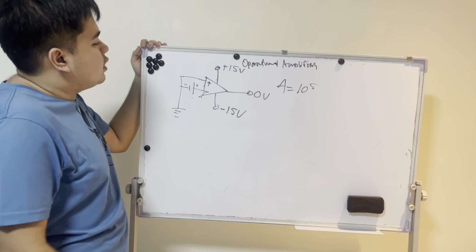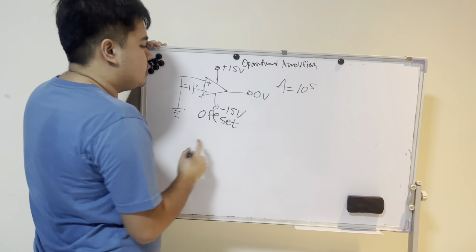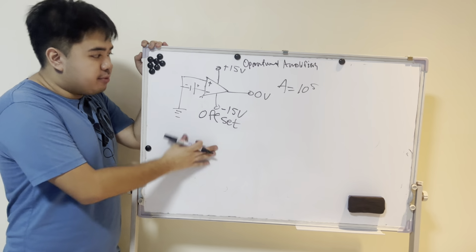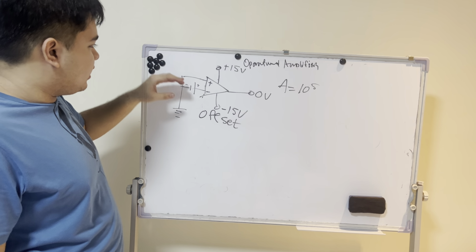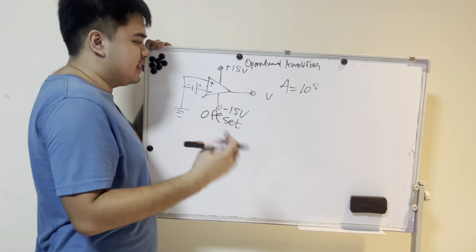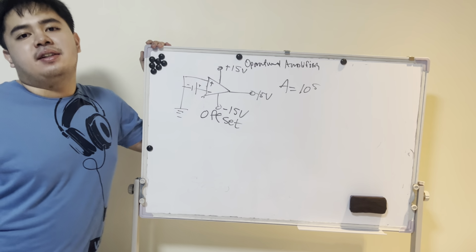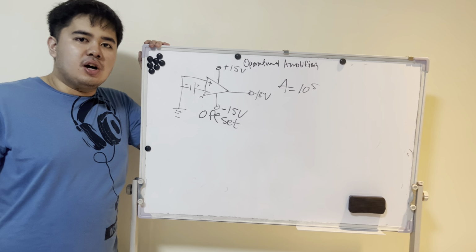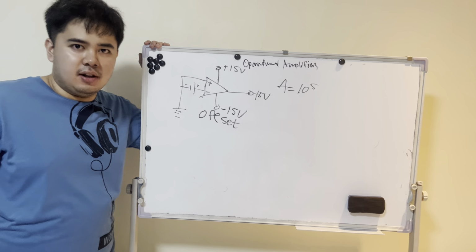So there is some offset voltage here, and this offset voltage is bad. Because if we had ground, nothing happening yet, this would not be 0 volts, even though it's intended to be 0 volts. This would show negative 15 volts. And that's bad. If we want to do the operations, we need this to have no offset at all.